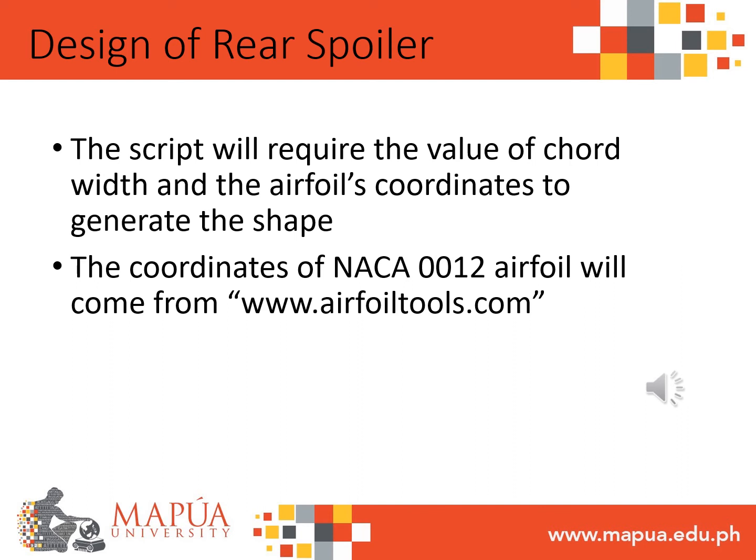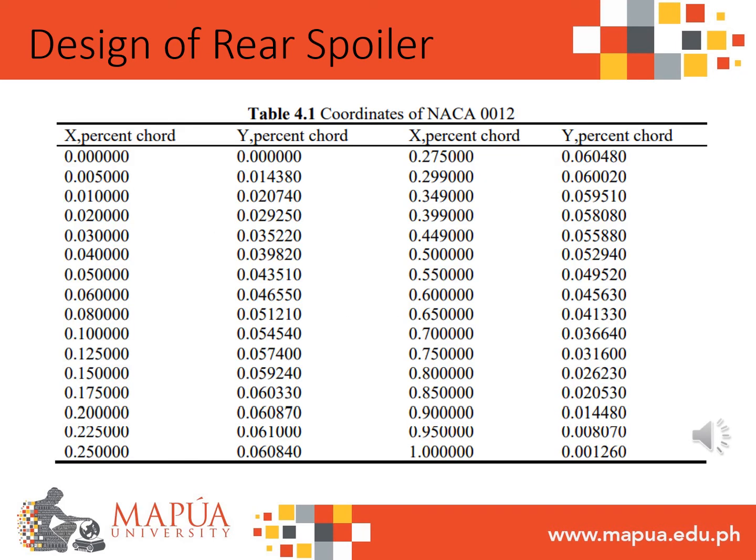The coordinates of NACA 0012 airfoil will come from www.airfoiltools.com. These are the coordinates of NACA 0012 in terms of percentage. We can get the actual coordinates by multiplying this percentage to our chord width.